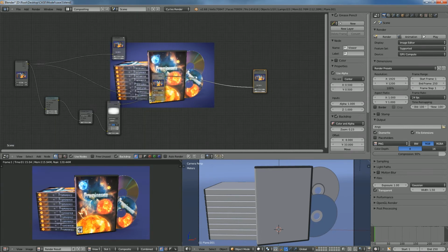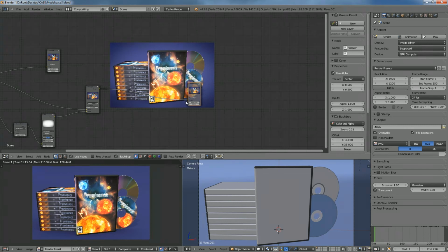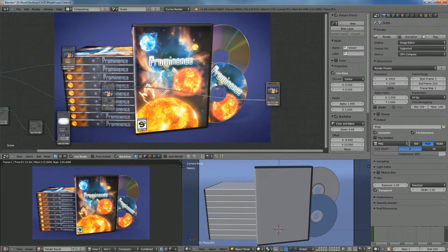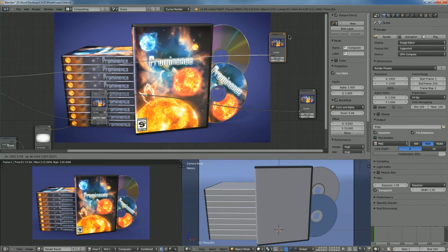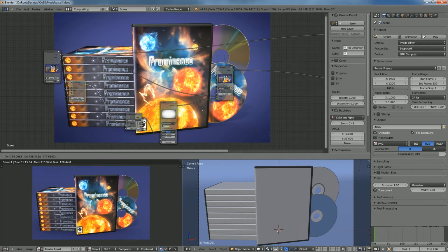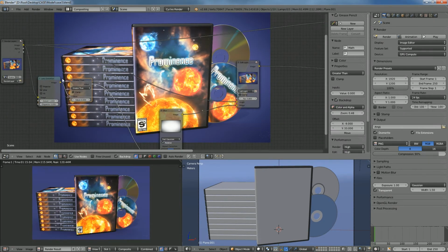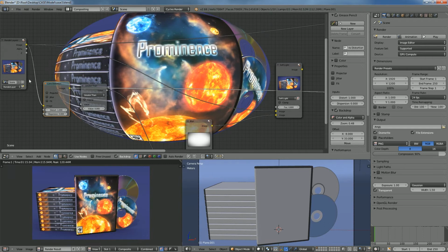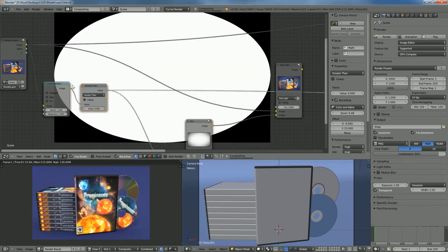And we'll just color correct this very slightly too. I'm just going to hit Alt-V to zoom in again, just so we can see what we're doing. And move our composite node over. Sorry, probably can't see a lot of this. So we have our original image feeding into a lens distortion. Actually, we can just go through these. So our lens distortion makes the oval here.